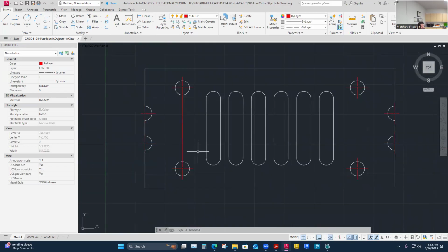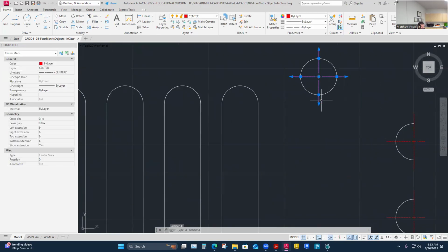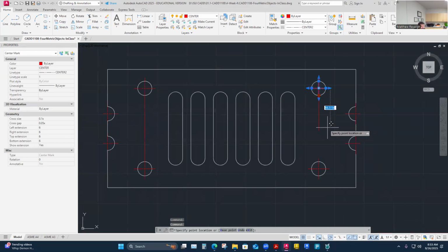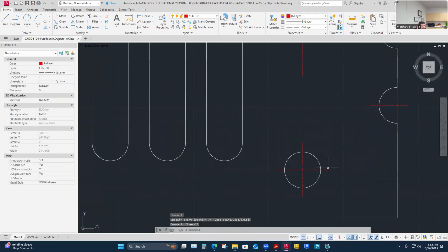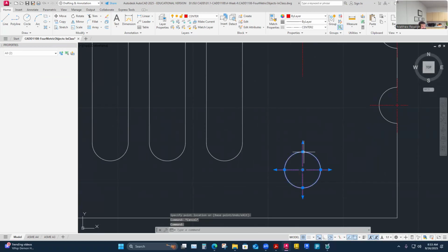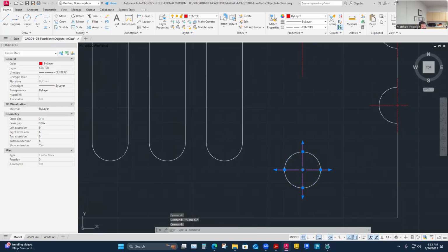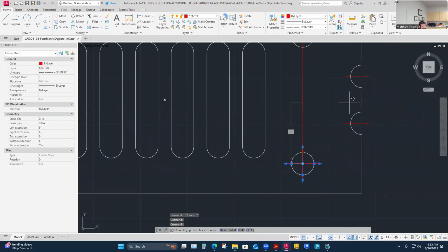Yep, I'll do it over here again. I just grab them from their main grip, and then I'm kind of referencing the center point. You see me drag over here to pick up that polar alignment. So I'm using that polar snap tracking, and you notice I use it a lot. It's just because I'm always looking for an alignment, and all you have to do is reference it.